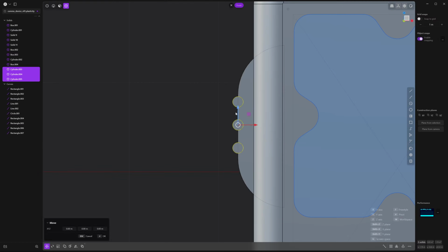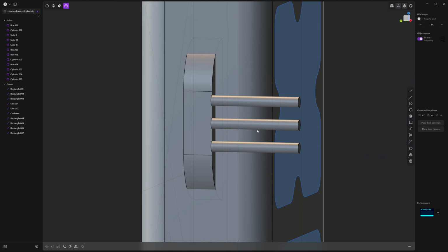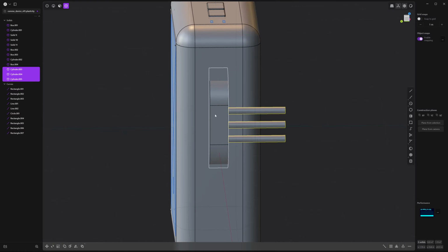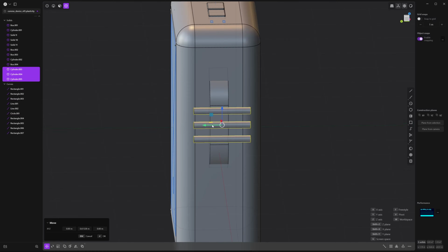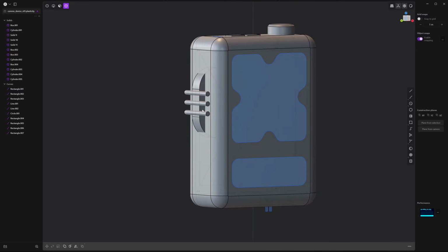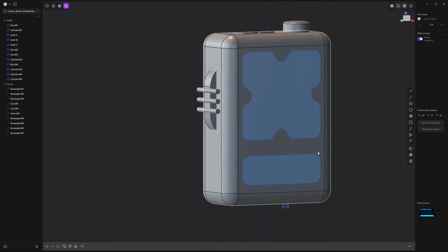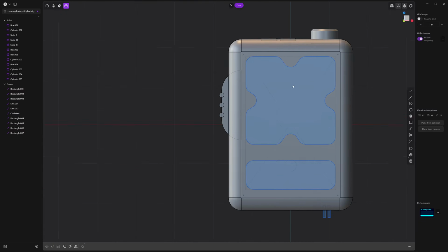And then press G so you can kind of adjust this Z axis, and Control so you can snap it to the center of that face. So now it should be centered. And we're not going to carry out the Boolean just yet, but let's just put it into place. Right now it's not touching that center area, so let's just move it in. It looks pretty good. Now I'm just going to drop in a couple more shapes and then move on to extruding these curves.